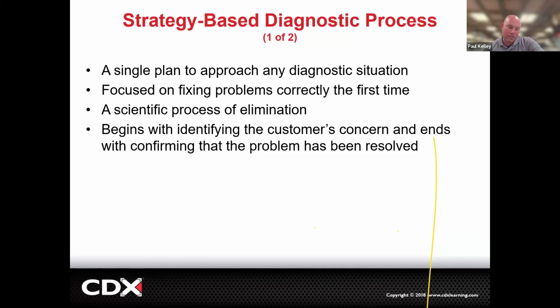And first off, we might have to ask quite a few questions because by default, the customer's going to say, "My AC doesn't work." They're not going to know. They're not going to give you the details. One of the first things we want to do is determine, is there airflow? If no, that may be like a blower motor issue. If yes, but it's warm,